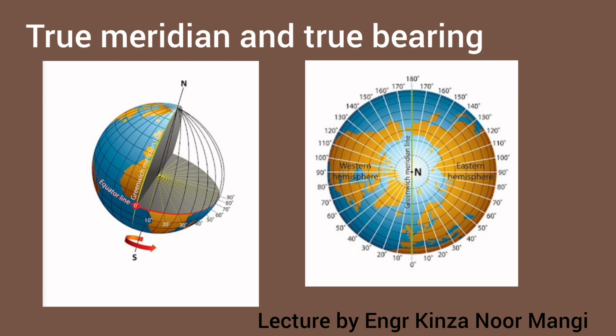Starting with the true meridian: the line or plane passing through the geographical north, the geographical south pole, and any point on the Earth's surface is known as the true meridian or geographical meridian. The true meridian at a station is constant. The true meridians passing through different points on the Earth's surface are not parallel but converge towards the poles. In surveys of small areas, the true meridians passing through different points are assumed parallel because of the small distances.